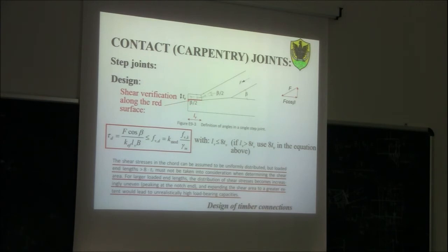No, this one was for the shear. These cracks are not cracks due to bending. Those cracks usually are cracks due to shrinkage. So there are natural cracks that form when wood dries up. Some cracks open, those cracks are usually horizontal, and they are going to reduce the resisting cross-section in shear.